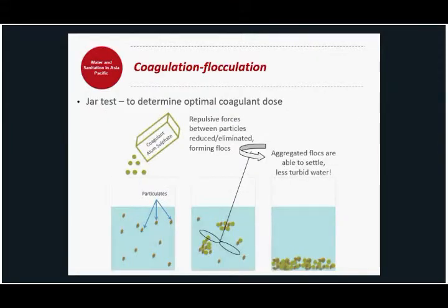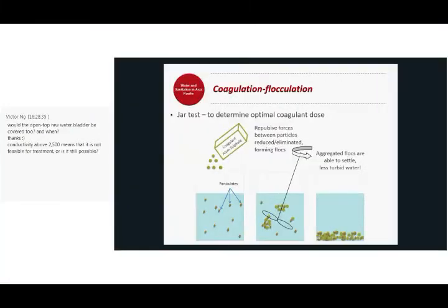To work out the dosing rates of chemicals for coagulation and flocculation, we usually perform a series of dosing experiments known as jar tests. We want to optimize the dose to get the best settling with the minimum amount of chemical, not only to keep the costs at a minimum, but also to avoid the carryover of aluminium or iron into the treated water. To do this effectively, we use a process called jar tests, and it is important to make sure we have clean tools, such as stirring sticks, jars, buckets, and syringes, so they give us the correct result. If testing for a source from a tap, we should try and let the source run for some time so that we get the correct water sample.